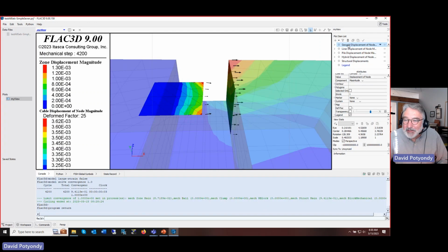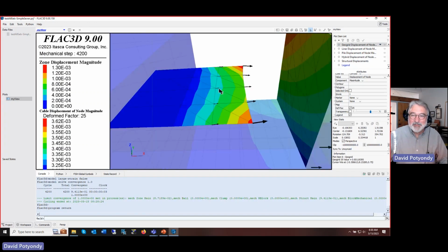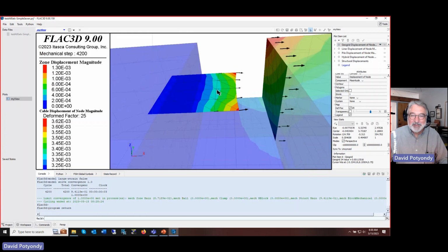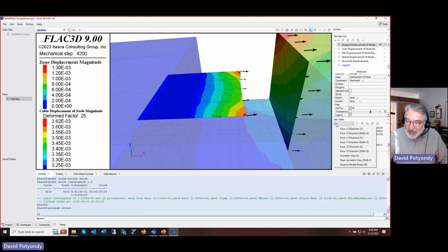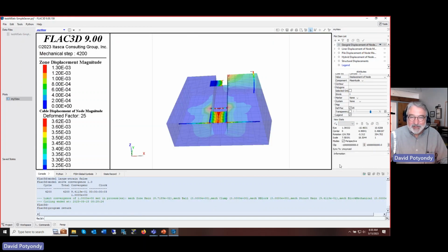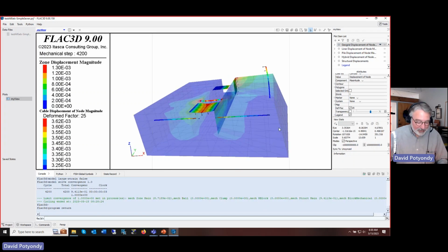Let's look at the geogrid. Deformation factor is not checked. So I'm going to say deformation factor 25, hit return. Now you can see how they're both being drawn with a magnification of 25. All right. Here's another useful thing. If you go to view stats and you get the left-hand guy, hit it, you can always choose reset the model extent. And that'll put you back in a system where it's beginning to make sense to you.